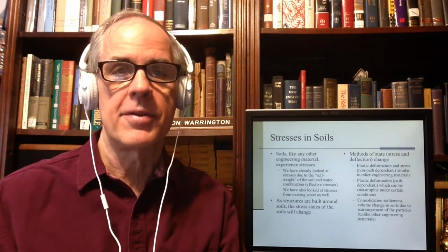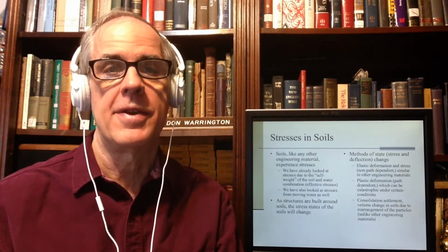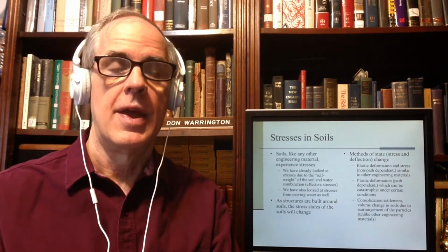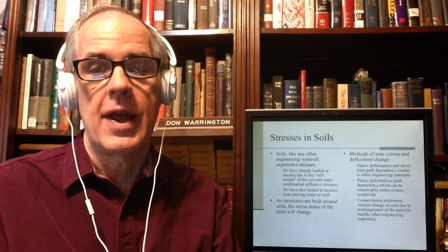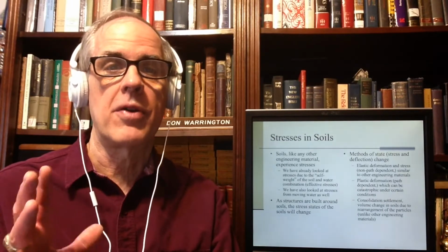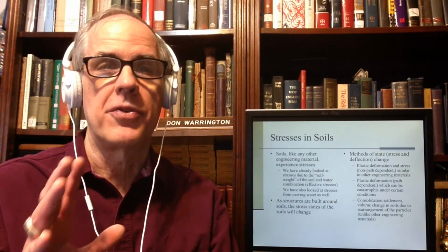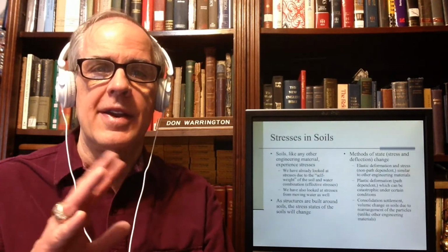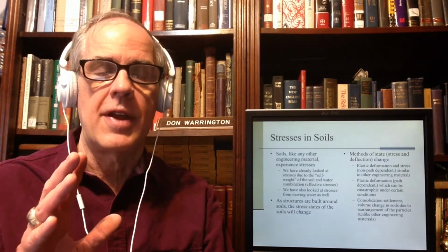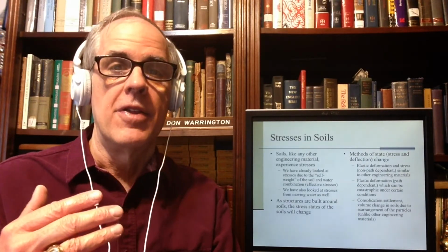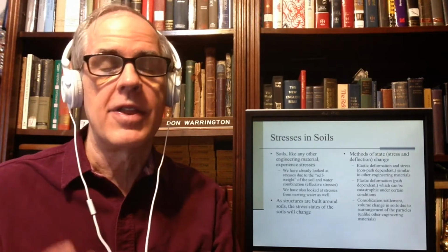Then there's plastic deformation, or path-dependent deformation, which can be catastrophic under certain conditions. I'm going to talk about how that works. And last but not least, we have consolidation settlement, which is a volume change during the soil particles rearranging. We talk about how the particles rearrange and the fact that their void ratios are different and can change. Back when we talked about relative density, we talked about the fact that the void ratio will change, and a lot of other things change too.